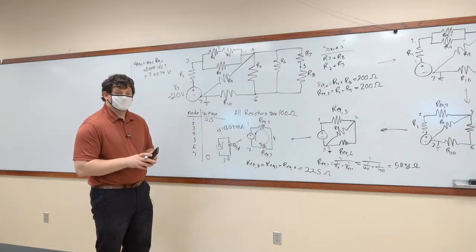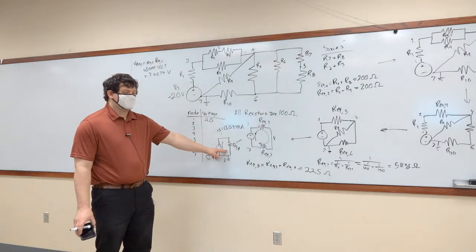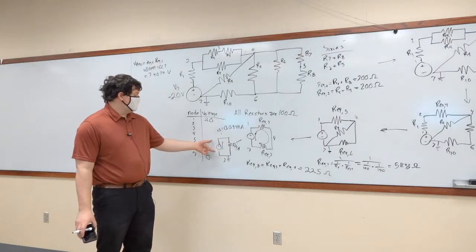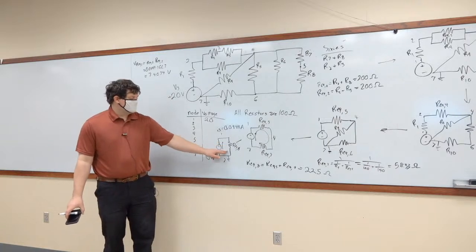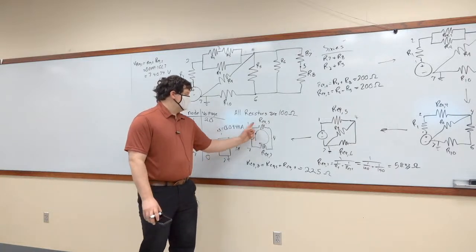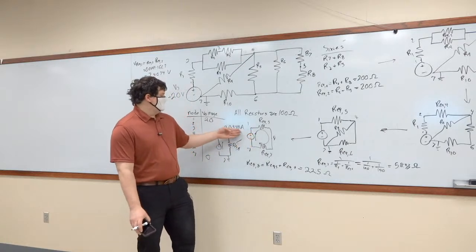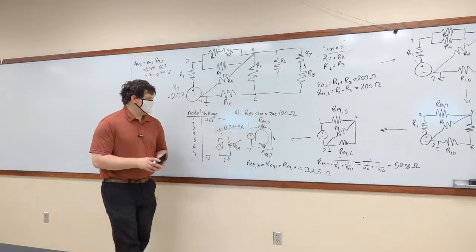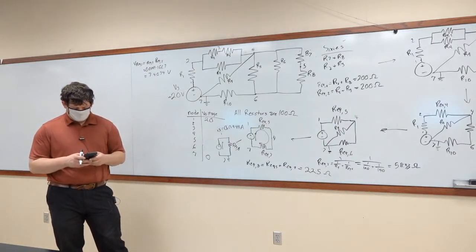We have to start from REQ8 and then calculate the current, right? Because you know what the voltage is across REQ8, you calculate what the current is through REQ8. The current going out of REQ8 is equal to the current coming out of the source. Current coming out of the source, calculated at 0.0444, which now I am questioning.